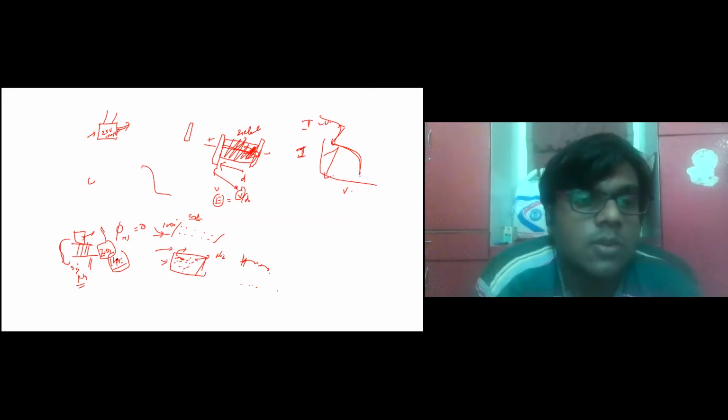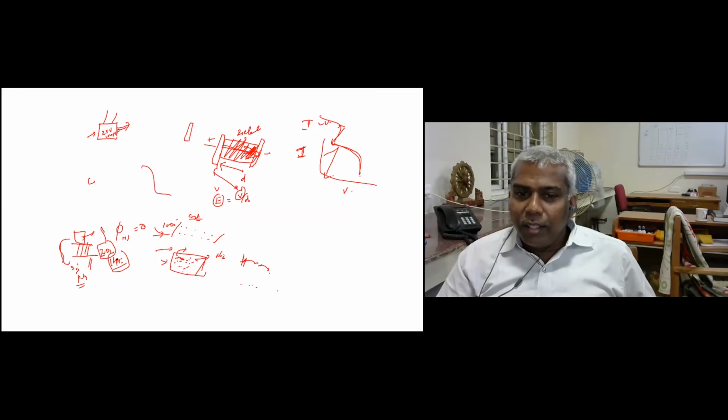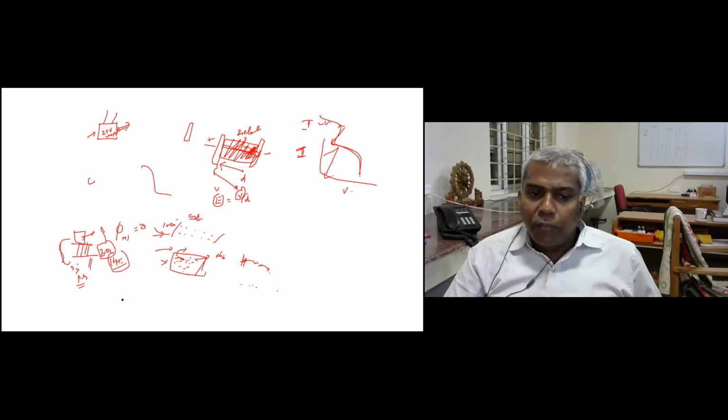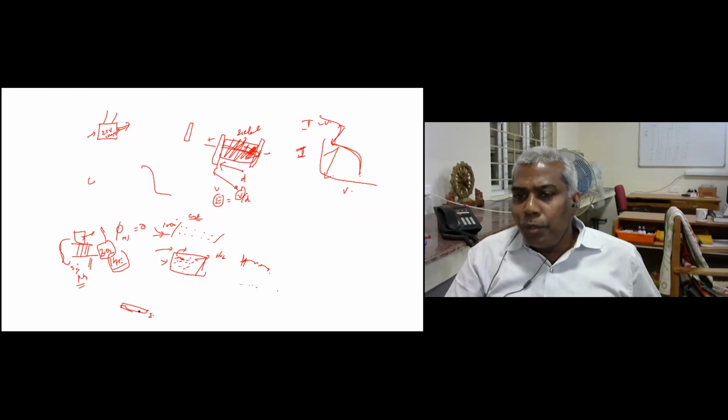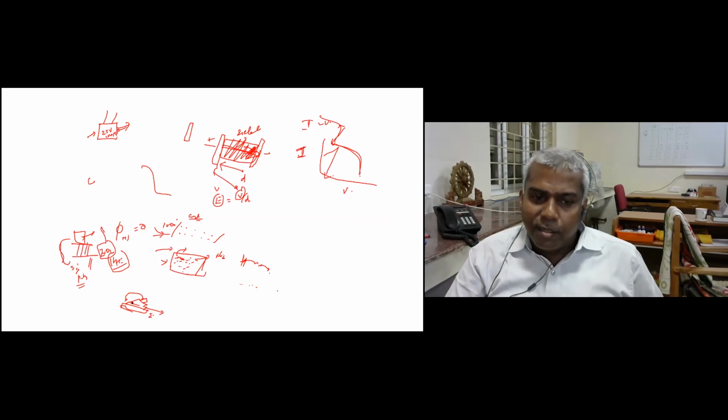Yes. So what are the advantages of MIM capacitors over MOS capacitors, sir? I don't think there is any great advantage. The only thing is that people have attempted many types. For example, you have a silicon substrate. In a MIM capacitor, you literally don't need a silicon substrate. But they wanted to have another coat here, a metal layer, and they take a contact from here. And they have an oxide layer, and another metal layer on that. So this is a metal insulator metal.